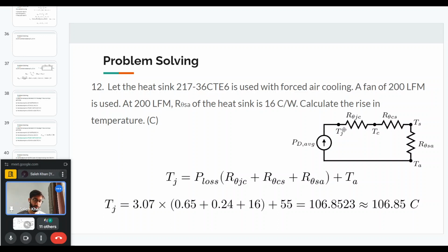That is the use of thermal paste. Beyond the paste, we also sometimes use an interface material, which is like a very thin sheet placed between the heatsink and the device, and sometimes it is used for insulation, like I mentioned, electrical insulation.